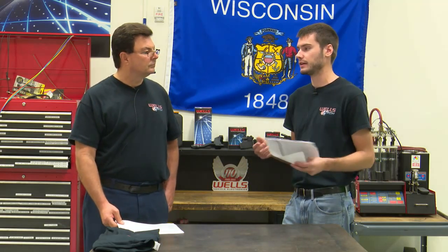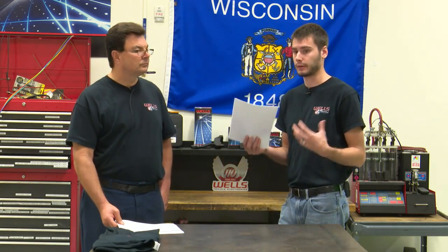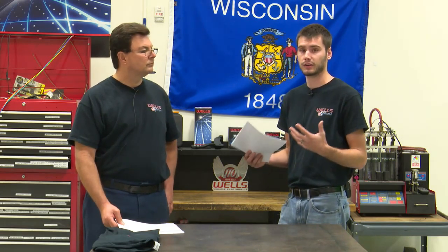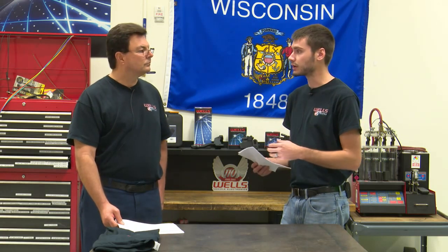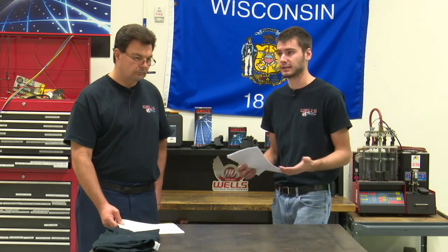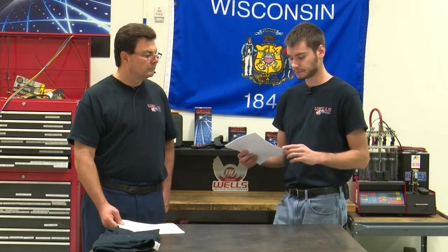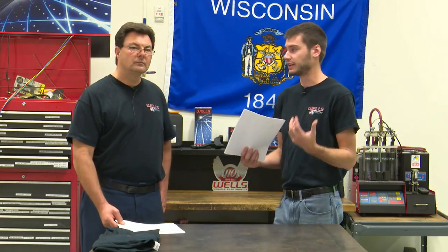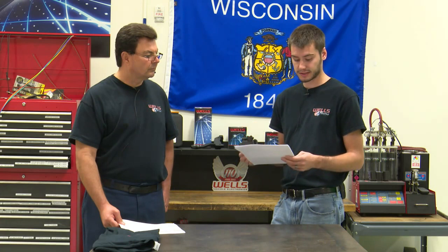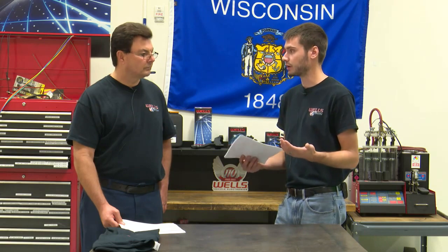So we've all run into this. A little example: customer comes in, check engine light for whatever, P0107. You fix it, you replace the MAP sensor, whatever it ends up needing. Vehicle goes out, it's running great, everything's fine. Customer comes back a few days later, maybe a week later, check engine light's on again. I mean, we've all seen that, right? Well, it could be because there was another code in there, another test that wasn't able to be run because it was set in that 107 code. So it could be that the TP sensor here wasn't functioning normal. The 107 was set so it wouldn't run the 121 code test.